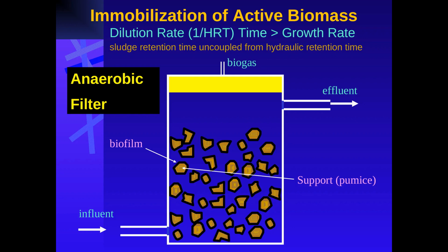The heart of high-rate anaerobic systems is the granular sludge. These granules are dense, compact biofilms with high settleability and mechanical strength. From a microbial perspective, they represent a balanced community of syntrophic partners, where different groups of microorganisms work together to break down organic matter. This close association provides protection from toxic shock and results in high methanogenic activity, leading to efficient biogas production.